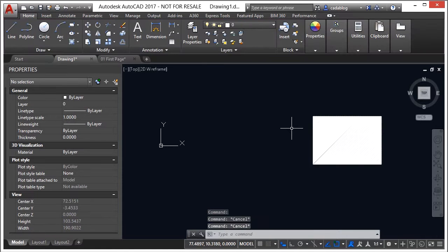The nice thing about this is that you can set up a layer for your hatch patterns to go on, set it as your default, then it will automatically create that layer in your drawings, even if the layer does not exist. Another item that Autodesk added is in units.